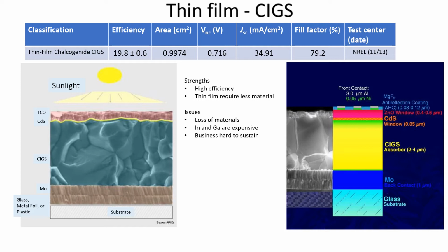The deposition of the materials can also be done without a vacuum, using bath deposition, spin coating of nanoparticles, or electroplating. However, these techniques are still under research. In recent years, printing techniques are being developed. CIGS deposited onto a flexible surface allows its versatile usage over curved surfaces and is free from the risk of shattering.